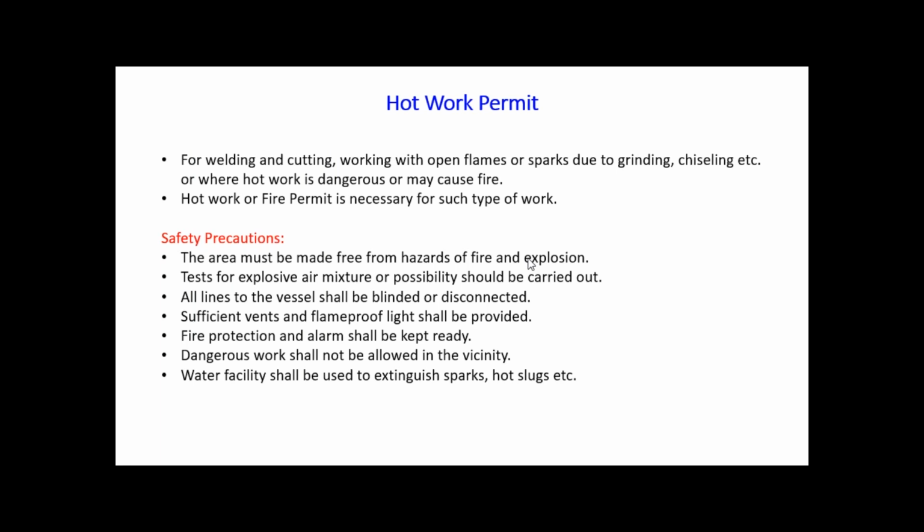One of the specific work permits is the hot work permit. For welding and cutting operations, working with open flames or sparks due to grinding, chiseling, etc., there are various activities which involve hot work, high temperature work, and that is why we have to go for the hot work permit system. Due to this hot work, there may be chances of fire. Due to the high temperature, there may also be a danger to human beings. Then a hot work or fire permit is necessary for such type of work.